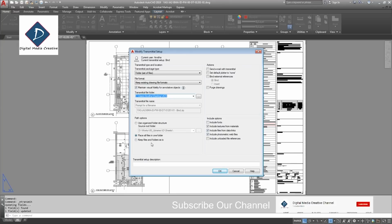So for sending not bound, you can just click here, then done. But for now I'm going to show binding. So I'm just clicking place files in one folder, and for the action I choose bind external reference and put bind.